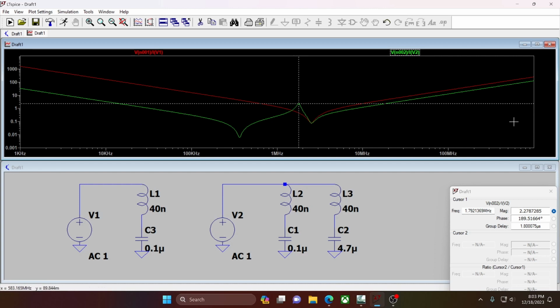At your high end, plane capacitance, assuming you are using a ground plane, you better be, plane capacitance that's built into the IC. That'll take care of the high frequency stuff.